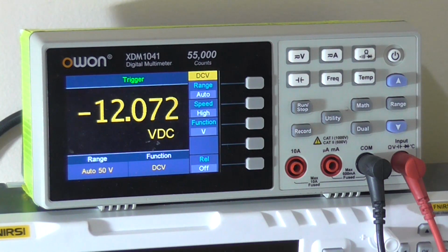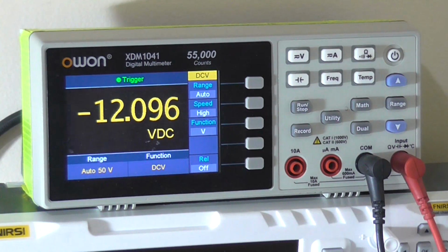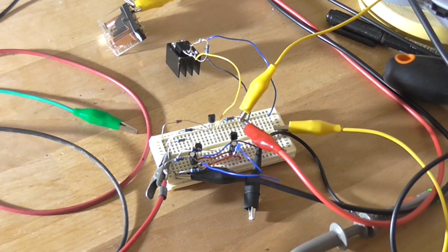And considering what I'm going to be using this circuit for in the end, it's not really going to be that much of a loss, because a plus minus 15 volt supply rail is going to be used as a supply for a preamp, for instance, or a bunch of op amps. So in my case, if it's only like 2 or 3 op amps, it's going to be about 20 mA of current draw. So we're not going to see that much of a voltage reduction.